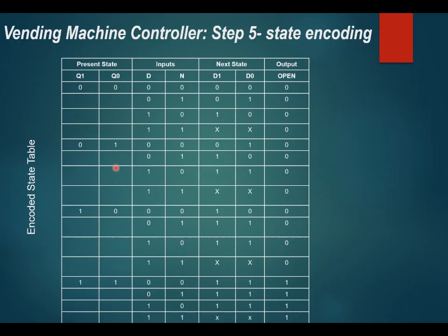Because a digital circuit can only understand binary signals, instead of symbols you need to make all the symbols binary values to represent them. Okay, so similarly, go to the next step. Once you have decided 0 cent is represented by 00, then all the 0 cent should be replaced by 00. All the 5 cent replaced by 01, all the 10 cent symbol replaced by 10, and all the 15 cent symbol replaced by 11.